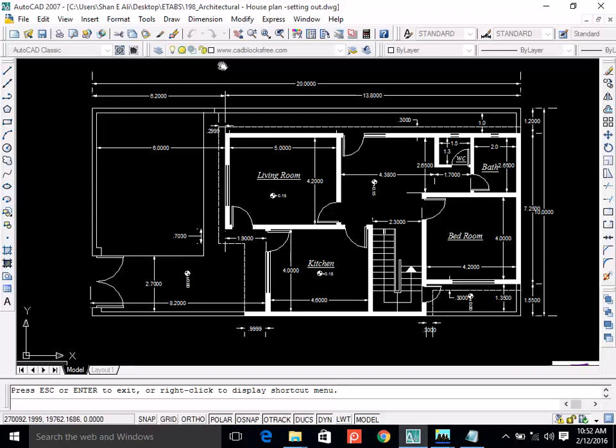It is laborious, and also you will make some approximations. So the better way is that you draw the grids in AutoCAD according to whatever the shape is, and then import those grids in ETABS.